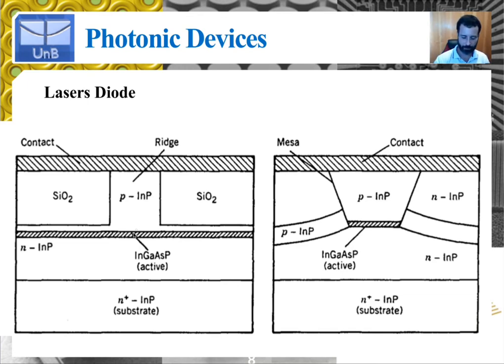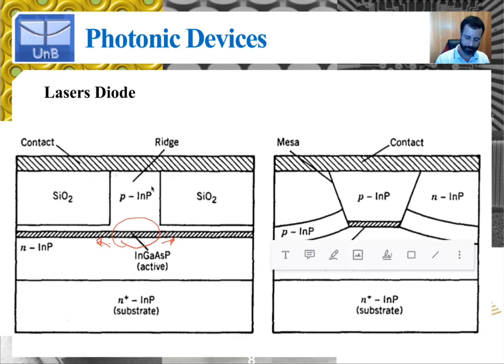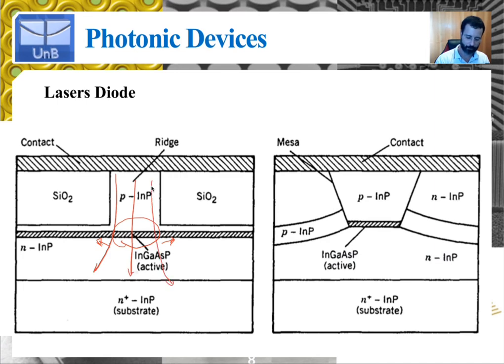So basically light will stay within this region here and not leak towards the lateral dimension right here, because once the current is flowing in this direction, if you forward bias the device, right, current would flow in this direction, the excess carrier concentration due to the current density J will make it so that this region, which has a larger carrier concentration, has a slightly larger refractive index than these lateral regions of the active layer on either side.